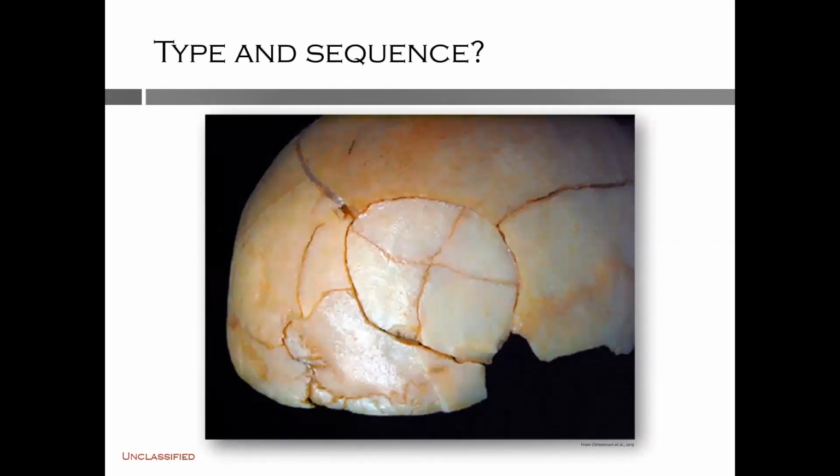In this case, the circular fracture came first, and this is a cone cracking event. The circular crack is continuous and therefore occurred first, and the discontinuous radial cracks came after. This is also an example of a cone crack resulting from a low velocity impact. The conoid here is large, and the cracks within the ring represent comminution of the conoid.